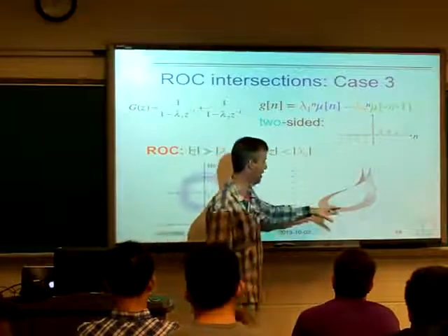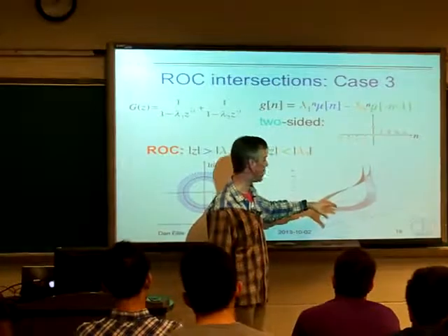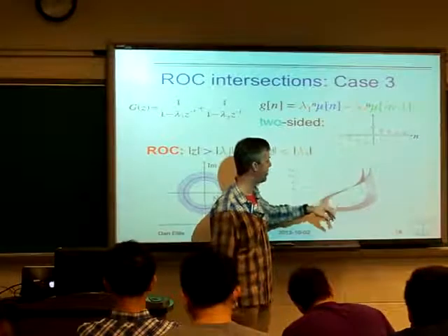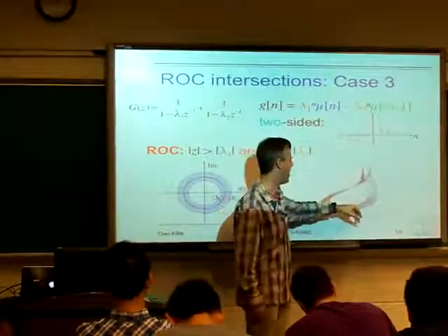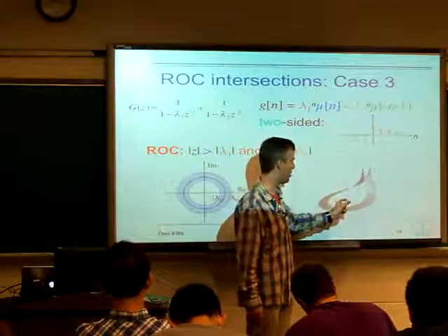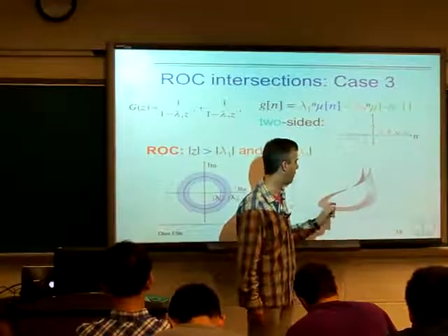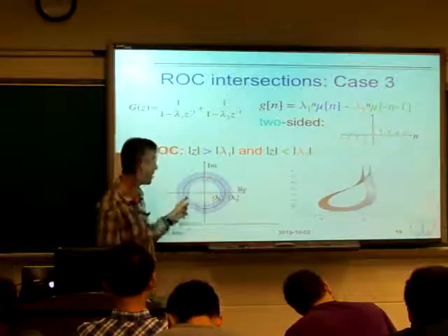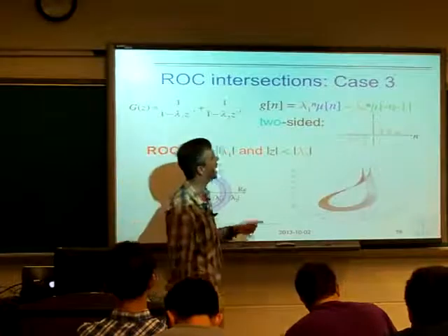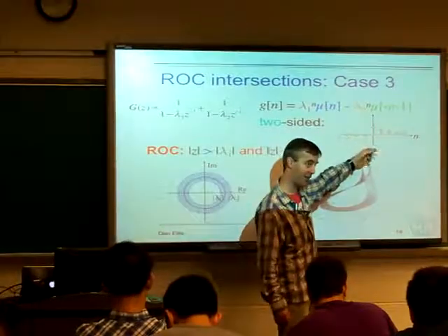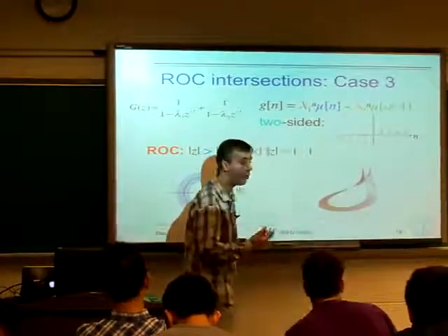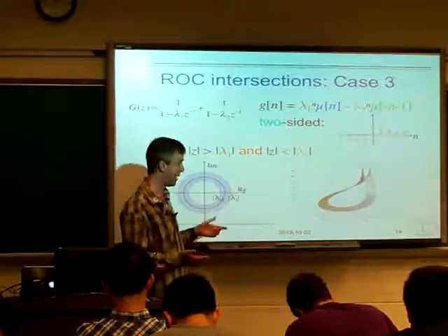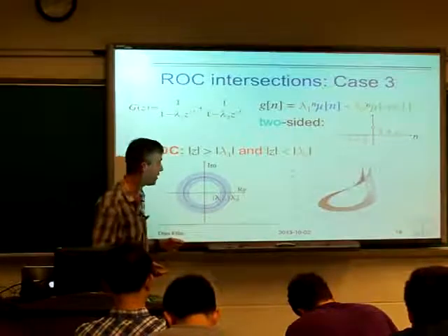And so again, we've plotted the entire z-transform magnitude here for all values of z, but where it's not visible, it's because it was divergent. But there's just a set of values of z over this fixed range of magnitudes where the sum converges. But now we notice that the unit circle is in the region of convergence, and this is a signal with bounded magnitude, something we can calculate its Fourier transform, and we can evaluate G of z for z equal to j omega.